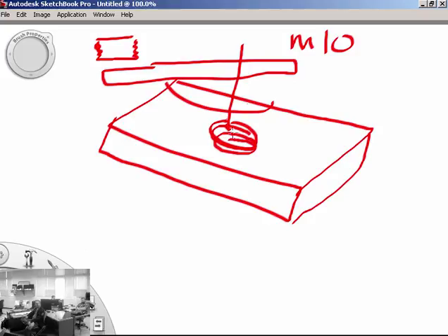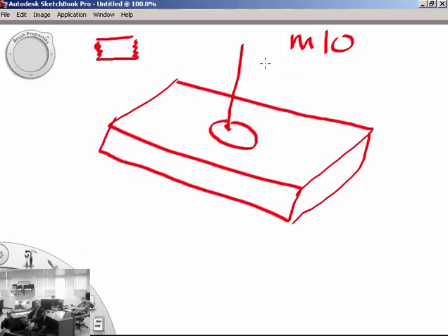So obviously you need to know which one to use in comparison to what someone is going to be using in terms of threads. Got to make sure it lines up. Doesn't work out too well to take an M10 bolt and stick it in an M8 threaded hole system, right? Now sometimes you'll get the odd characteristic where it does sort of work. Not nearly those size differences, but it does sort of work, but it has a little slop.